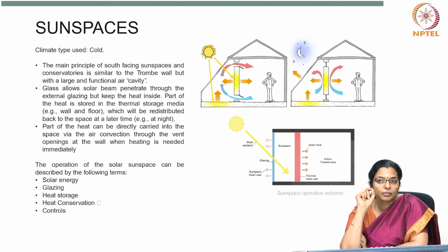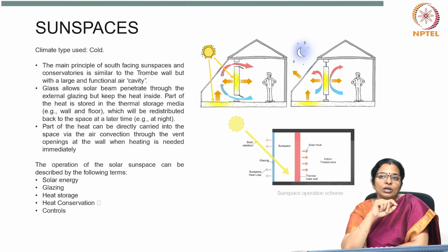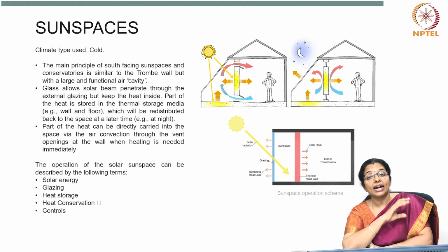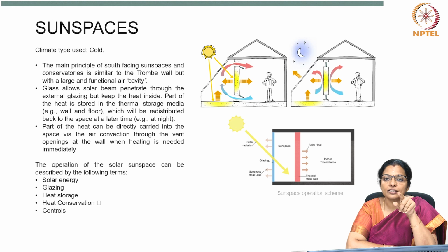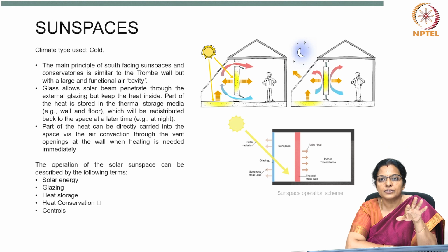Orientation must be proper. So, in order to achieve optimization in design, the glazing has to be perpendicular to the radiation received at any time. Heat storage: the first phase of the heat storage procedure is the solar radiation absorption. The surface color and texture are the two main parameters that affect the absorptance.